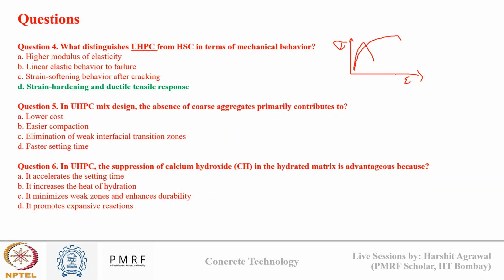Behavior in tension, and this means that it can carry tensile load or compressive load even after cracking, and it exhibits a ductile response instead of the brittle response that we get in a high strength concrete, because there are fibers. So fibers will provide some strain hardening and ductile tension response.